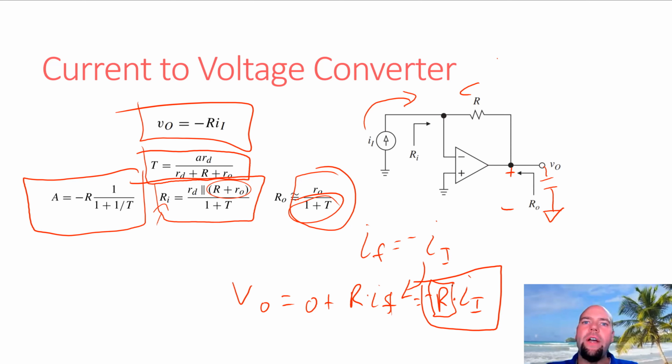Welcome back. So after about 5 minutes of you working on that problem, you probably got that if you have a nanoamp current and you need to convert it to 1 volt, you need the inverse of 1 nano, which is 1 giga ohm, or "jigga ohm" if you're doing Back to the Future terminology. So 1 giga ohm resistor, that's pretty big resistor. Can you get it? Yeah, you can get a 1 giga ohm resistor.